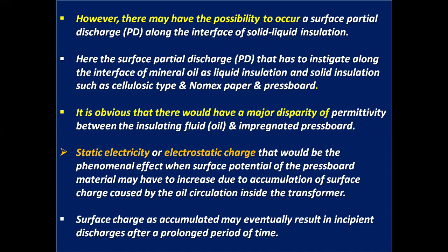Here, the surface partial discharge instigates along the interface of the mineral oil as liquid insulation and solid insulation such as cellulosic type and Nomex paper and pressboard. It's obvious that there would be a major disparity of permittivity between the insulating fluid, that is oil, and impregnated pressboard.